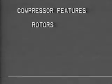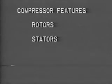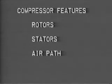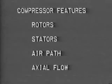Here's a brief review of what you've learned. The basic features of the compressor include rotors, rows of moving blades; stators, rows of stationary blades; air path, decreasing in size forward to aft; axial flow, air flow parallel to the compressor rotor axis.